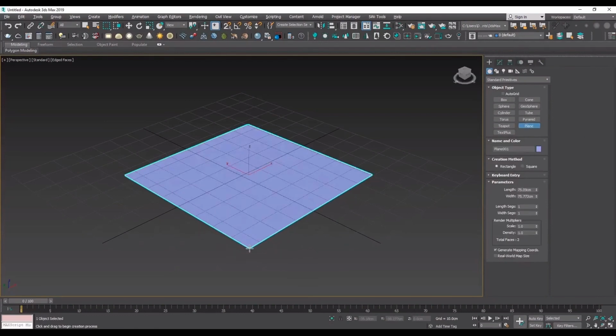In 3ds Max, I add a plane, and let us begin. Our first step is to clarify and find out how TurboSmooth works, because it's a very important concept in hard surface modeling. We must have clear understanding of how it works. In regular box modeling, though, at times we might get what we want without using TurboSmooth, but here it plays a very important role. By knowing how TurboSmooth works and its behaviors with the techniques we're going to learn here, we'll be able to model absolutely, or almost better say, anything we want.